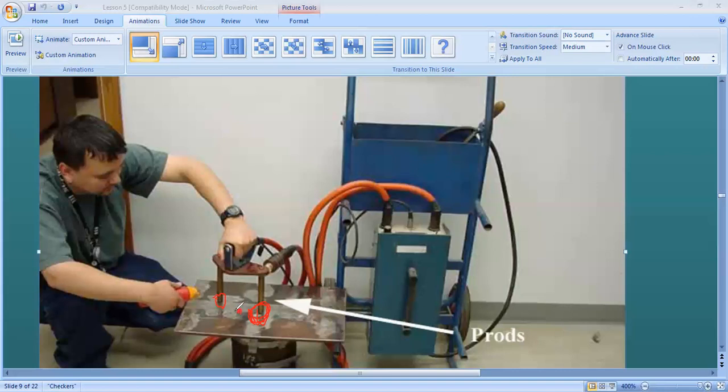Now if you are reducing this pole distance, because this is flexible, this is not permanent. These are the permanent type of prods, but we can adjust the distance, less or more. If this distance is less, then the magnetic field here will be different. If you are increasing the prod spacing, then we have to increase the current. So the current calculation is based on the distance between prods. If the distance between prods is less, the current value will be less. If the distance is high, we have to increase the current.